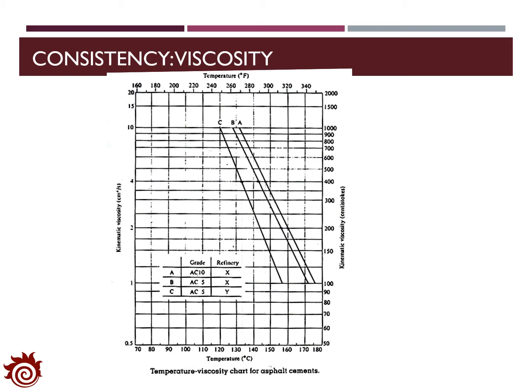The figure here demonstrates the relationship between the kinematic viscosity with respect to the temperature for three different types of asphalt cement. Clearly, we can see that with a higher temperature, the kinematic viscosity will be smaller, and you will observe the linear relationship between the viscosity and the temperature.